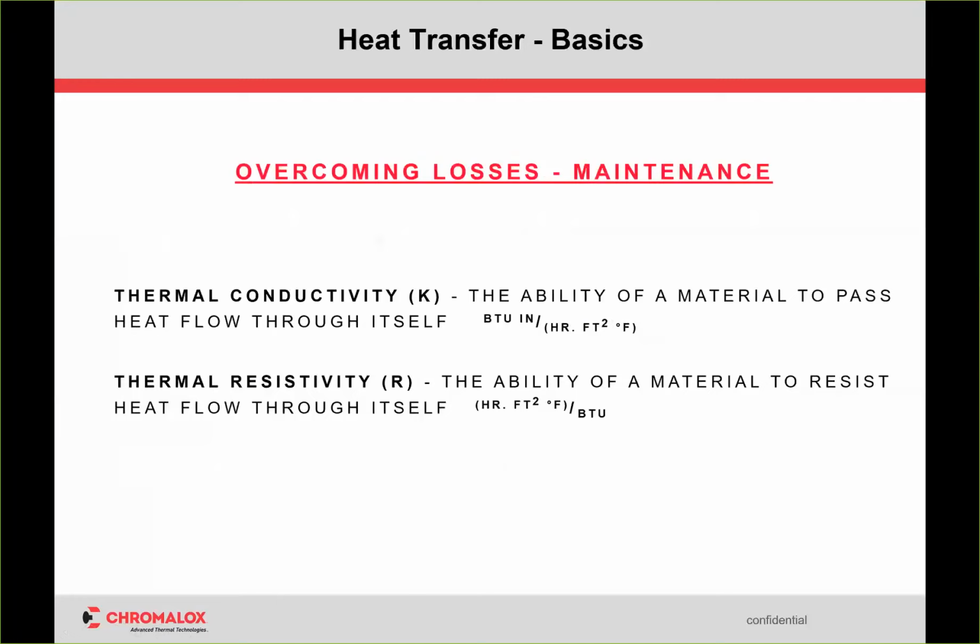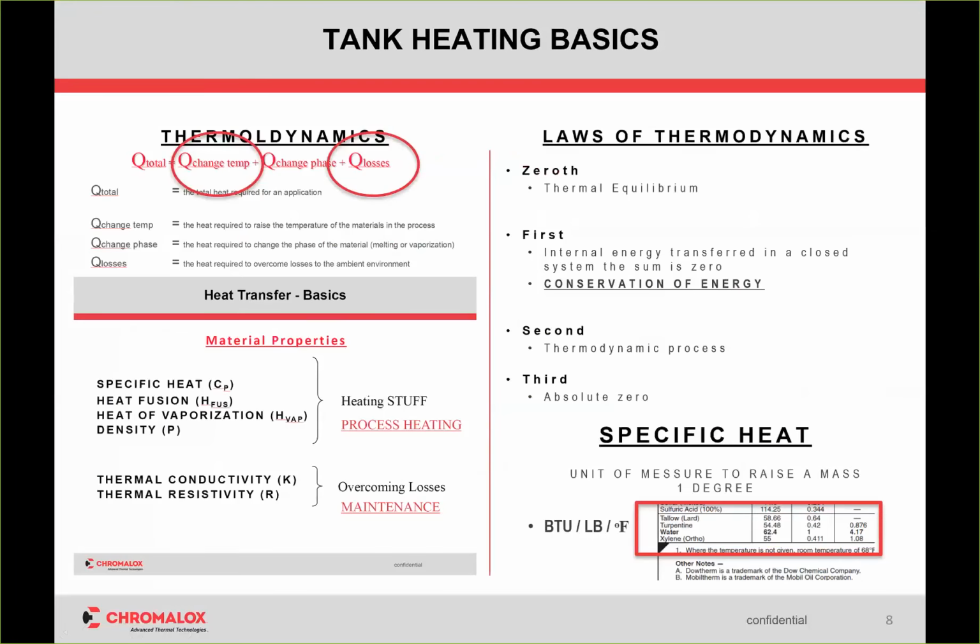They need the ability to heat up in the case of a shutdown, maybe in the case of a startup. And you want to walk through that with the customer. Hey, have you considered this? And those factors are the thermal conductivity and the thermal resistivity. That is K and R. Now, K is commonly referred to as U as well, and we'll talk about that in detail, but we don't need to waste a whole lot of time on that because we have calculators for that.